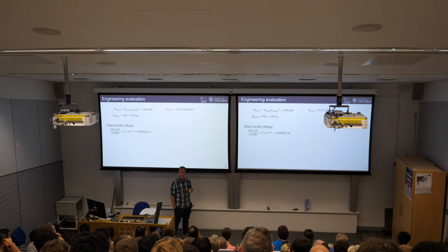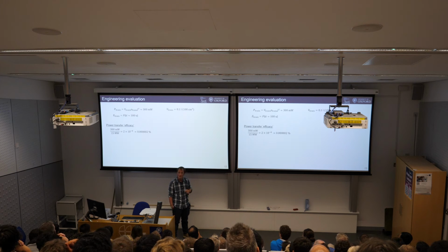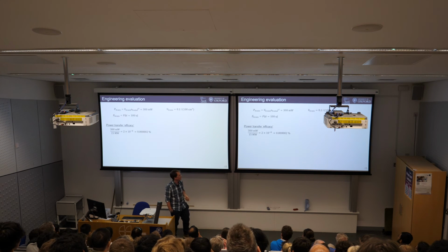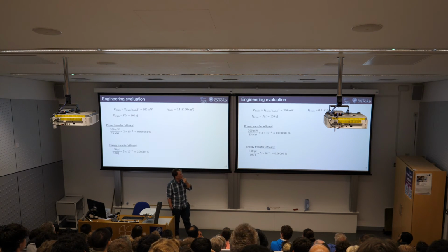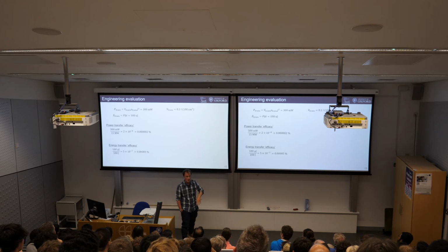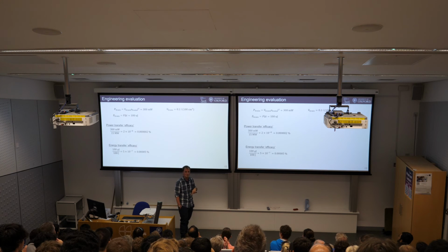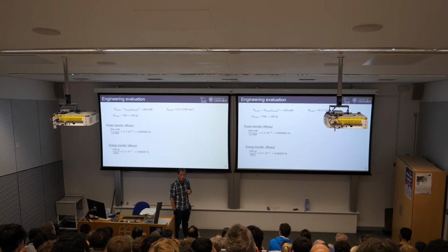Think about the power transfer efficacy of this system. I said we're putting 15 megawatts in peak, and I'm saying we're getting 300 milliwatts of effect in the brain. That is not a very big number. Fine. Think about how much energy we're transferring. Okay, we've got 100 microjoules dumped into the brain, but I had to put 188 joules into the coil in the first place to get that to happen. Also not a very big number.